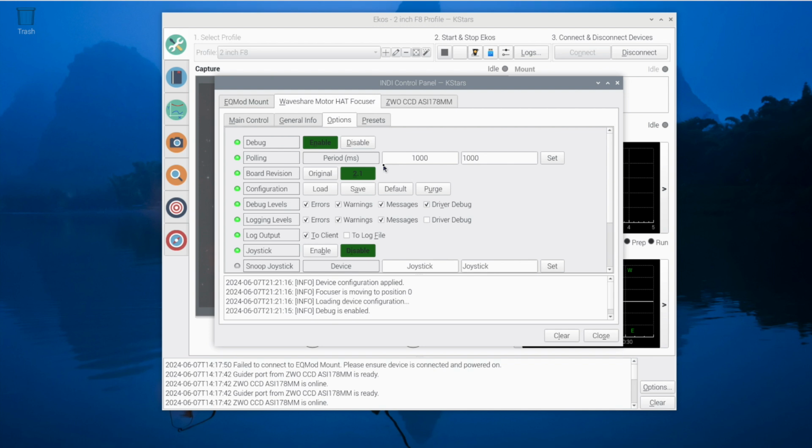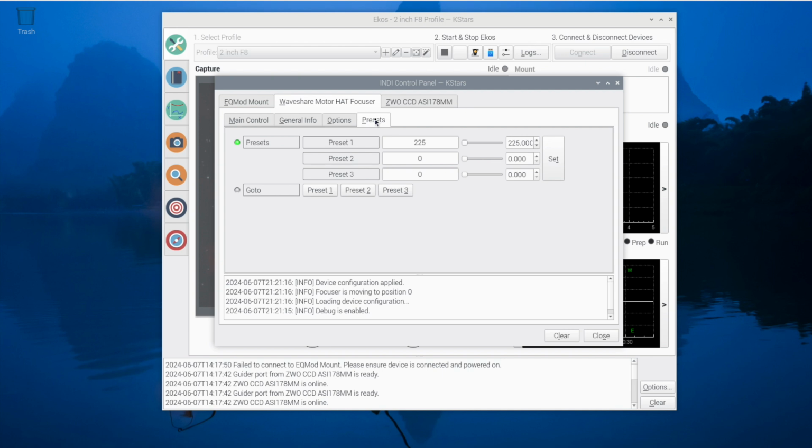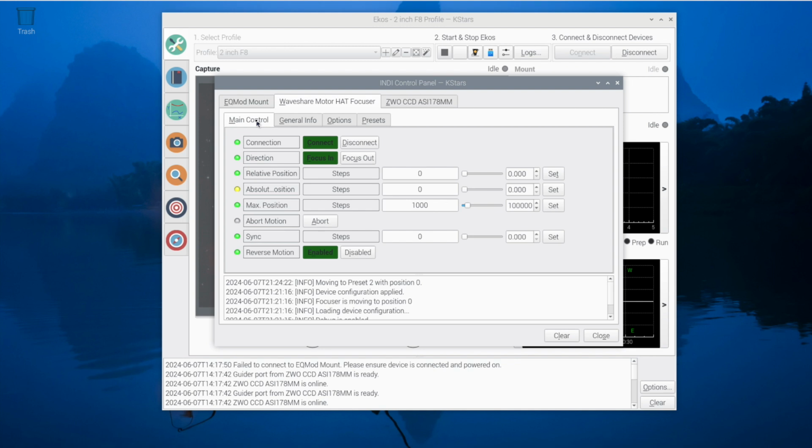And then, come to think of it, there's one further thing that you need to do, and that is that at the end of your session you need to go to the home position and then shut it off. Otherwise, what will happen is that when it fires back up, it loads the configuration and thinks it's at 0, and you could be in the middle and it's not really 0.